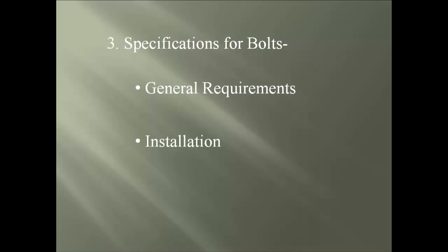The second item of this topic is the installation, which covers snug tightened, pre-tensioned, turn of the nut, calibrated wrench, twist off, and direct tension indicator methods that require the following variables to be verified: